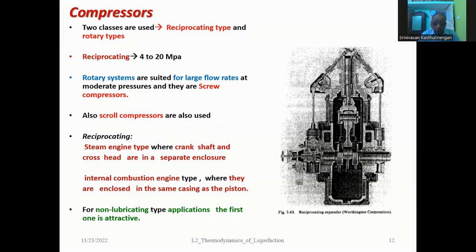Okay. In place of these types of compressors, one can also use what are called scroll compressors. In the scroll compressors, there are two scrolls: one static scroll, against which another scroll is rotating, which is the rotating scroll. The gap in between the scrolls will carry the gas. As the scroll rotates, the low pressure gas gradually gets converted to high pressure gas, and at the exit, by choosing appropriate valves, the gas will be transferred to a high pressure zone. Okay. Now,